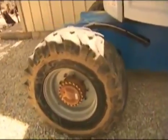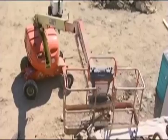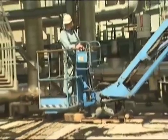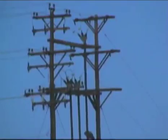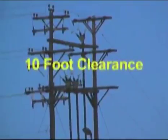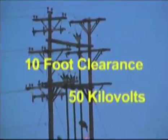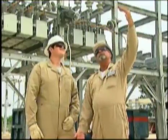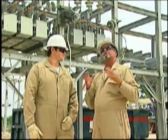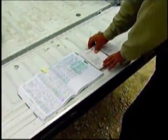Hazards that may create dangerous driving conditions, such as overhead power lines, holes, drop-offs, bumps, lumber, tools, and debris must be identified, and procedures to avoid any hazards made known to all employees. OSHA requires personnel to maintain at least a 10-foot clearance of all power lines with less than 50 kilovolts. If a power line has more than 50 kilovolts, additional distance is required. Employees should consult with their supervisor to determine the proper distance needed. Electricians have different guidelines and should consult with their employers concerning this issue.